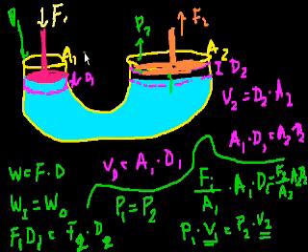Well, you can do this example in multiple situations, but I like to think of it without gravity first, because gravity tends to confuse things, but we'll introduce gravity in a video or two. When you have any external pressure onto a liquid, so onto an incompressible fluid, that pressure is distributed evenly throughout the fluid.